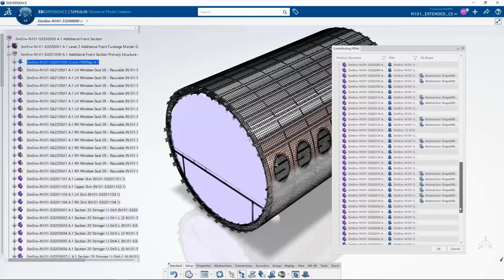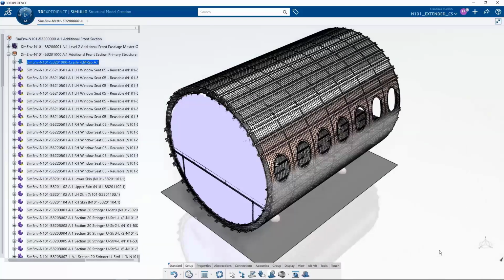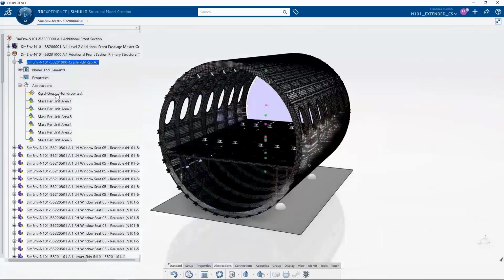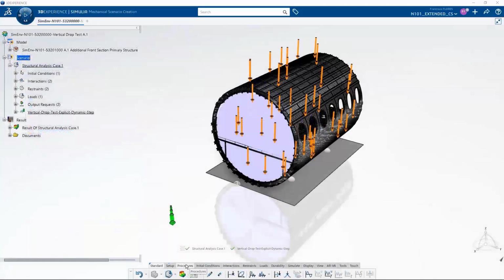Of course, this procedure works well on simple parts. On the more complicated parts, typically what will fail is the mid-surface extraction, so it will require some manual intervention. But for simple parts, the automated mid-surfacing and meshing works pretty well.